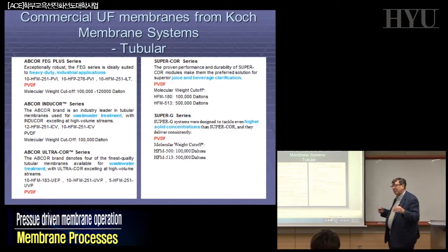No results until now because companies don't want to change and don't want to give too much information. So when you find a cutoff, remember that if your PVDF membrane has a cutoff of, say, 100,000, you have to read how it is measured. Is it measured with dextran at pH 5 or with polyethylene glycol at pH 2, etc.? Because depending on the situation, if you're smart, you understand a little bit how the real selectivity of your system is.